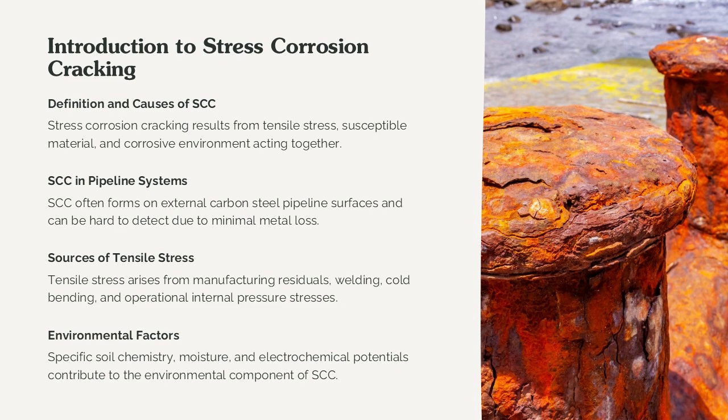The tensile stress component may arise from residual stresses from manufacturing, welding, or cold bending, as well as operational stresses from internal pressure. The environmental component typically involves specific soil chemistries, moisture conditions, and electrochemical potentials. SCC is particularly dangerous because cracks can grow over time and coalesce, potentially leading to sudden rupture without significant warning. Understanding the fundamental mechanisms of SCC is essential for appreciating why targeted assessment methodologies such as SCCDA are necessary and why reliance on general corrosion indicators alone is insufficient.